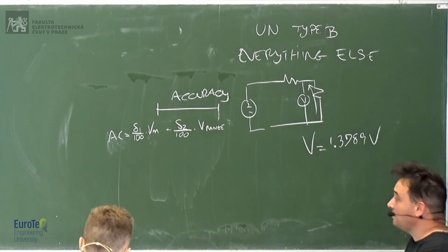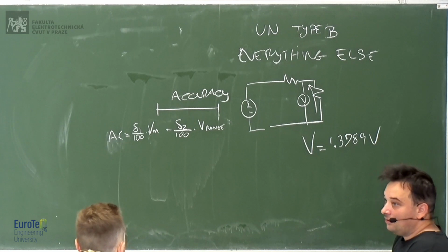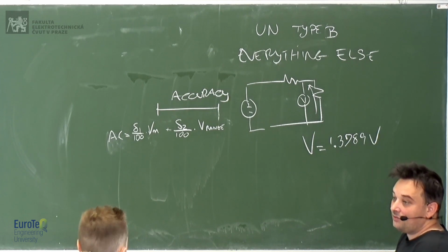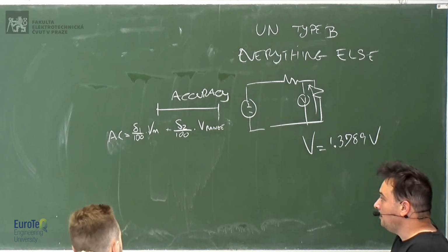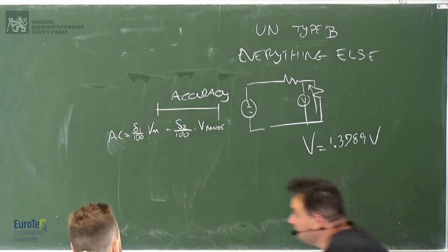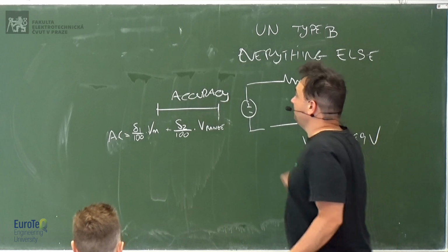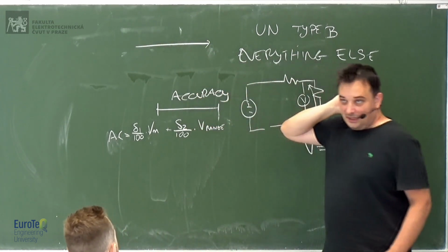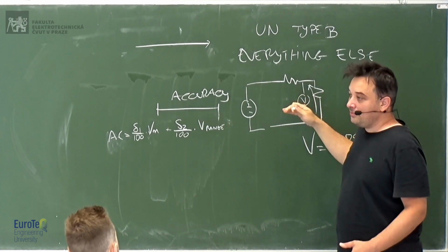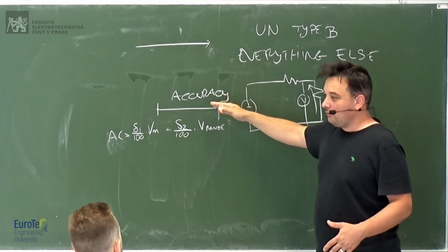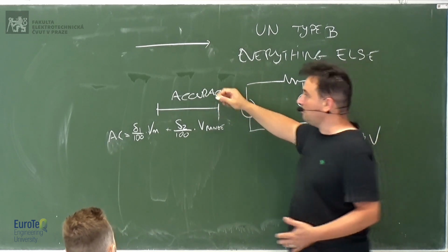In other cases, the accuracy is given as a percentage of the range. They tell you the accuracy class is 1%, meaning 1% of the range. Then that's the problem, because theoretically you would need a distribution of probability of the measurement in that range of accuracy.